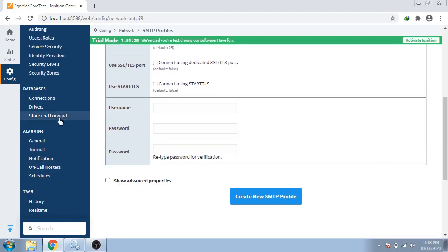Now you are set. See the alarming and the connection. First of all, it is an Ignition rule that Ignition only connects to Ethernet PLCs, not those that have Modbus connections or RS-232, 485, because Ignition only supports Ethernet now. First you need to connect the first PLC to the second PLC through Modbus or any other communication network, then you connect your first PLC to Ignition.